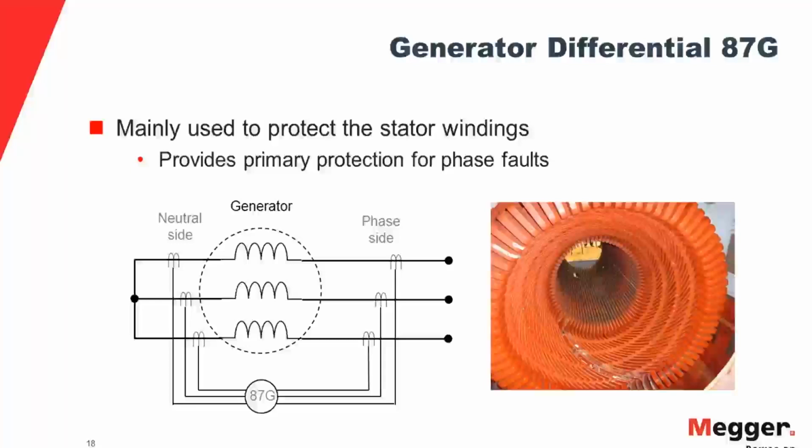So, in summary, we talked about the basics of the differential protection. We also talked about what a percentage differential protection is. We talked about the slope characteristics, why we have dual slope or multiple slope, and we talked about high impedance differential function. I hope that should provide a comprehensive explanation on the basics of differential protection. Now, let's talk something about the applications. How do we implement these protection schemes in order to protect the assets of the power system?